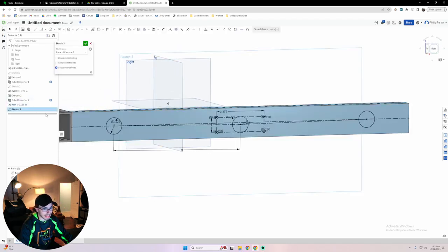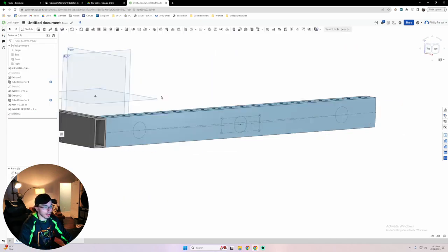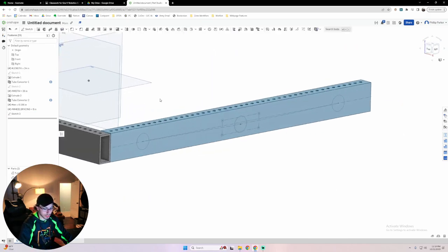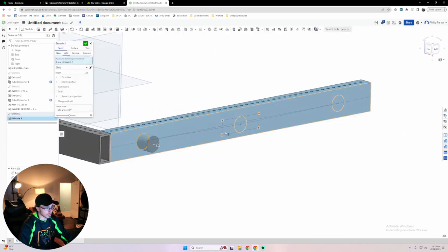And to make it even better, instead of using the number 9, I can use a new variable as wheel distance or wheel spacing. Wheel spacing, 9 inches, enter, boom. Okay. And finally, I can press Shift E and I can extrude.